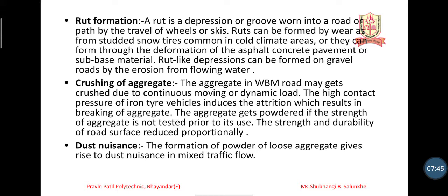What is a rut? While constructing the road, if it is not properly compacted, if it is not properly constructed, then obviously after some time, if vehicular load or the tire is going over that particular area for a longer period of time, in that same part, then you can see after some days the rut of the tire is there, and because of that the crack is forming.